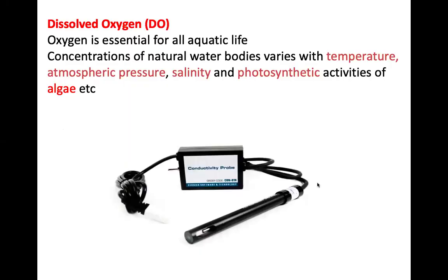And this is a conductivity probe that can also be recalibrated to measure the dissolved oxygen. And this is essential for all aquatic life. Dissolved oxygen content can also be affected by temperature, pressure, salinity, and other photosynthetic activities of organisms like algae and other organisms that are present in the given water body.